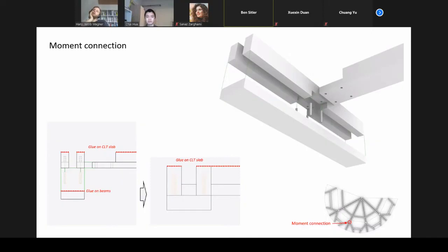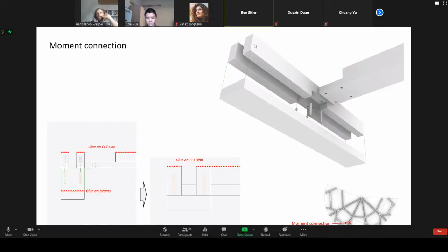Oh, sorry, LVL for these beams. 3 plies in LVL would be like 6 millimeters or something. Yeah, but this section would be one LVL beam section. So you could chop the beam into smaller pieces and then re-glue it back up on site. Yeah, but that would be adding a lot of glue to the project.